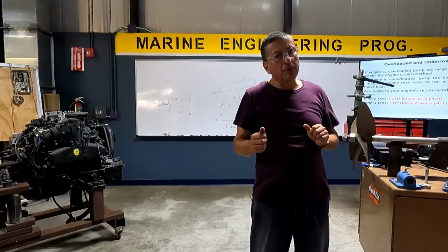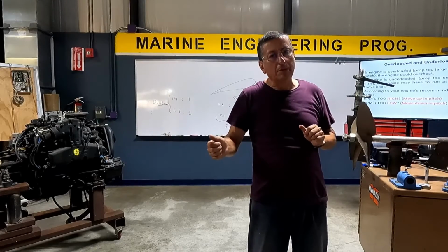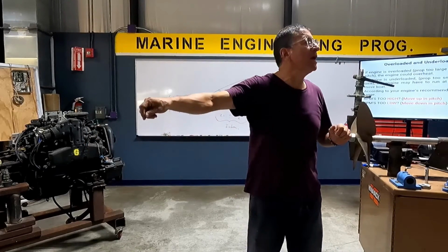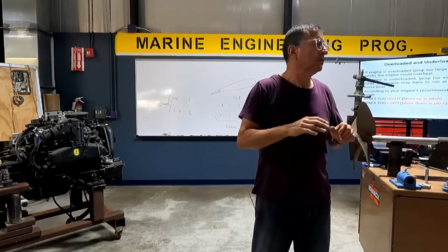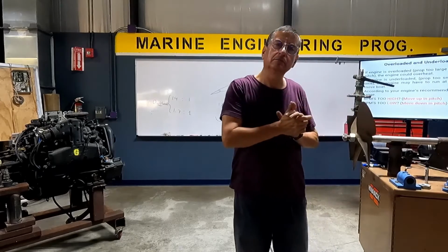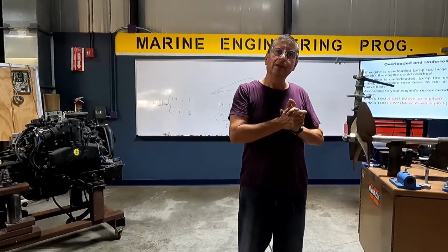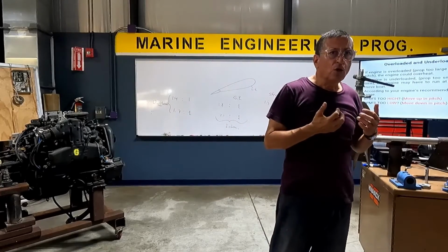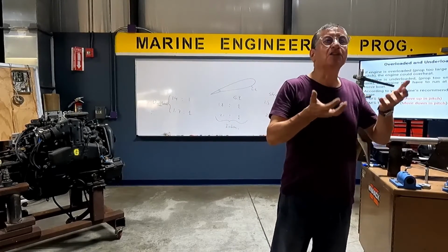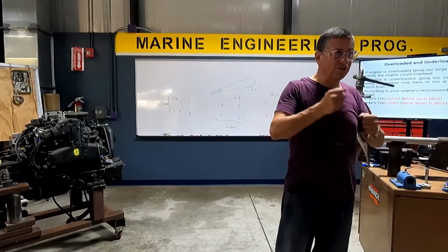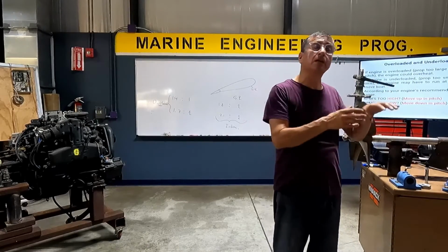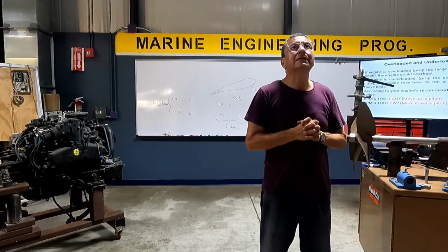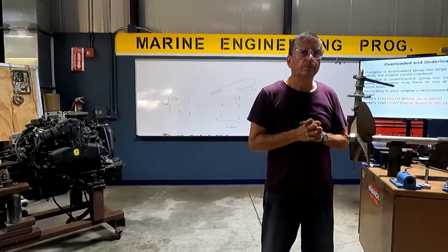Then less torque, more RPMs. The last one is maximum RPMs and minimum torque, exactly the torque of the engine. That's the function of the transmission: increase the torque and reduce the RPMs, or the reverse. And it protects the engine and the bearings. Later we are going to talk about that. That's the gear ratio.